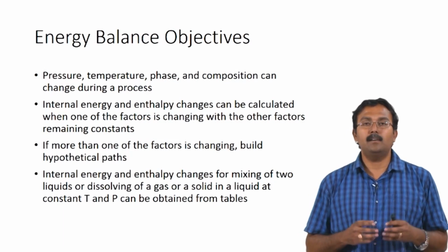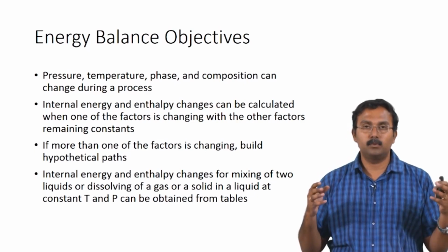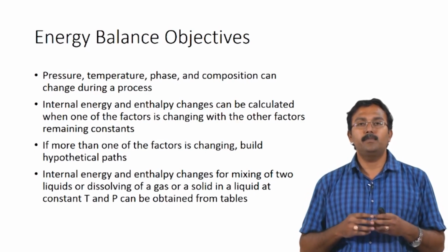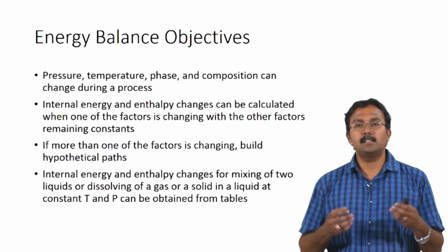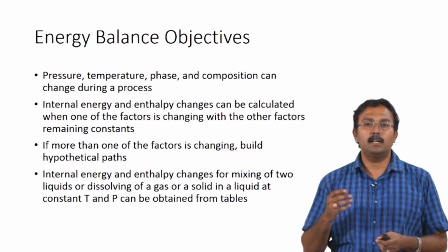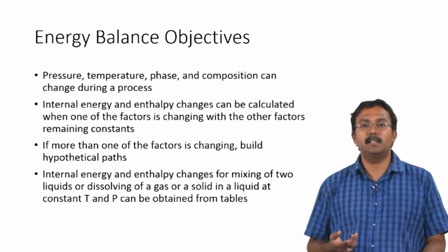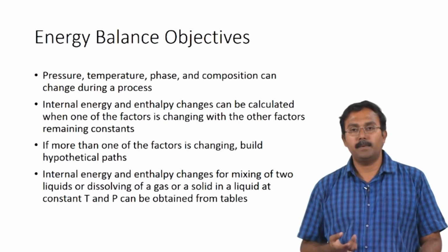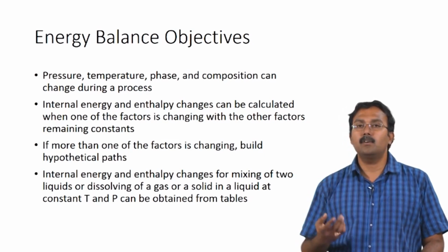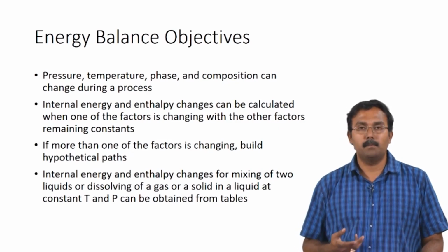So, you can also have internal energy and enthalpy changes when there are two components mixing. So, if the components are ideal gases or similar liquids, you can ignore this. However, for dissimilar liquids, or when you have a gas or a solid dissolving in a liquid at a constant temperature and pressure, you would have to account for enthalpy of mixing and solutions. This can be obtained from tables.